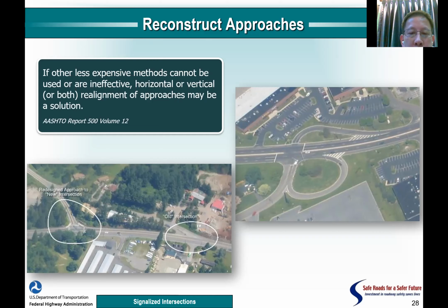Like this, it's not good because one may not know which one is the main road. Earlier, maybe this is the old road, a good road, and the newer road came, and then there are accidents here. The new approach is to build the intersection as close to a right angle as possible, so that everybody can see each other well.